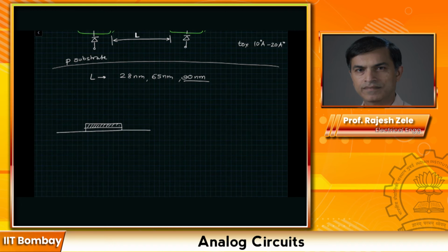After depositing polysilicon, if you do doping of phosphorus in this fashion, the phosphorus would get into this region like this, and also into the polysilicon here. Because we are doping it with phosphorus, the polysilicon will start acting like a metal, since it has a lot of free electrons. And these are our doping regions, which are for source and drain.